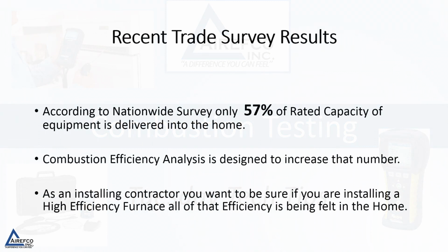According to a nationwide survey, only 57% of rated capacity of equipment is delivered into the home. Combustion efficiency analysis is designed to increase that number. As an installing contractor, you want to be sure if you are installing a high efficiency furnace that all of the efficiency is being felt in the home.